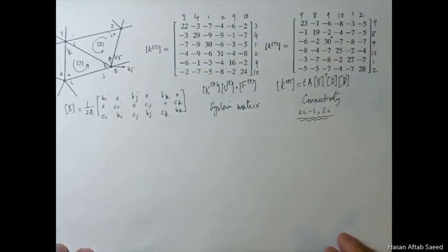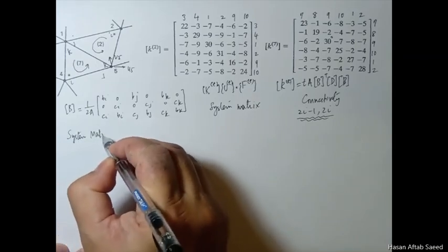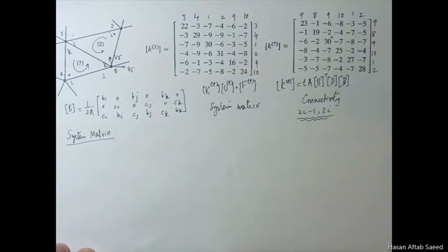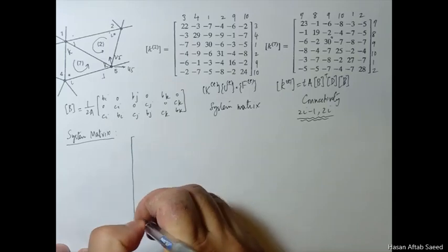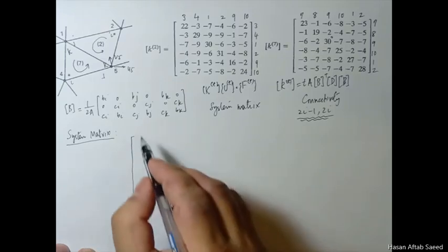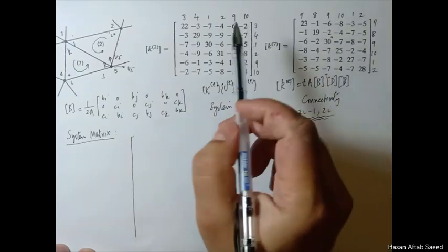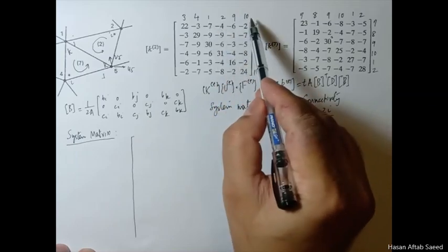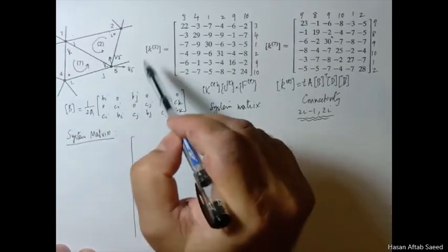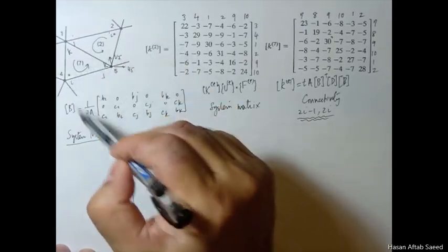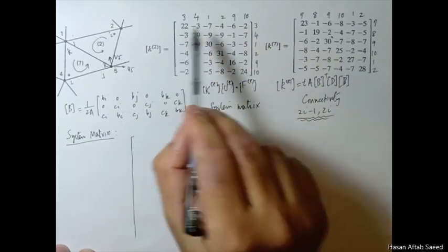Now what remains is very simply mapping to the system matrix. Let's assemble that. First of all, we must create a placeholder, and by placeholder I mean all the degrees of freedom that are likely to appear. In this case, we know that at least from 1 to 10 we have, and it's reasonable to assume that if there are other elements around here, because this system is not just 2 elements, then there'll be other degrees of freedom too, but at least 1 to 10 we have.